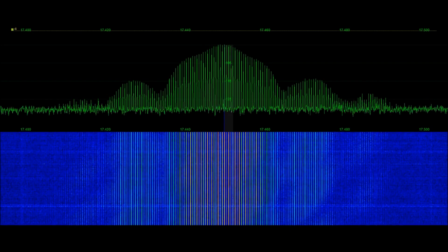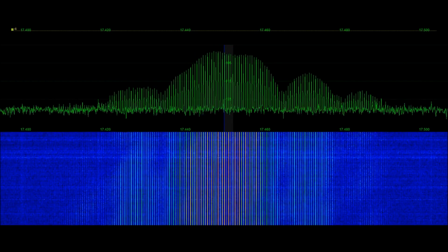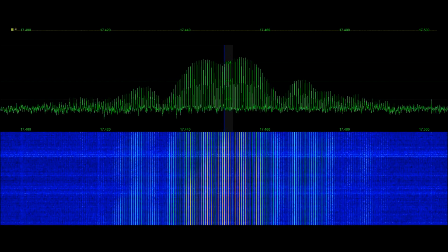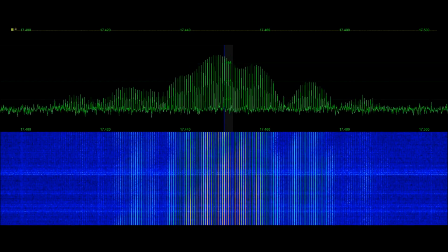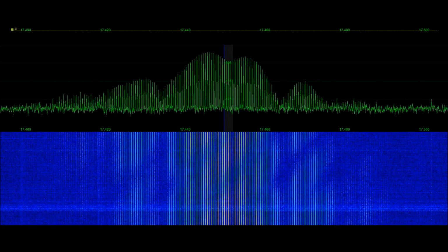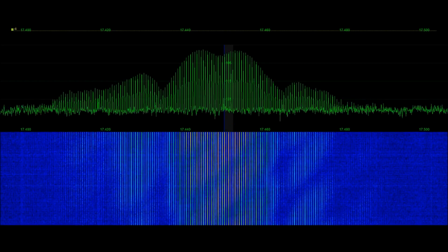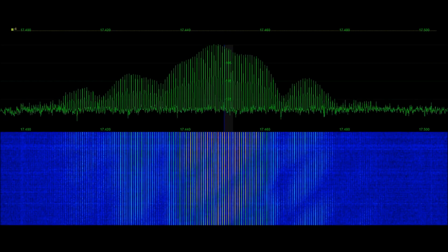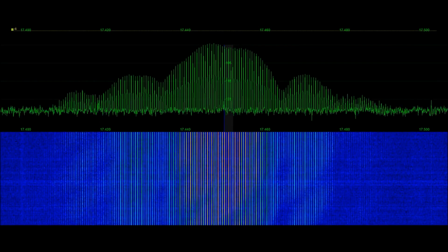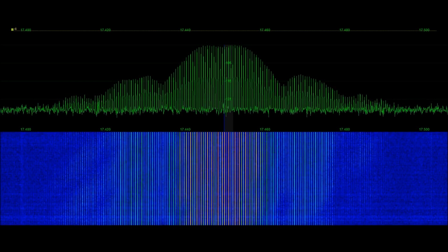And you can see the sidebands actually develop here, the upper and lower sideband of the main lobe that we're looking at. And this is really problematic because this is a Doppler radar, and the sidebands not only take away energy from the fundamental lobe, but they can also cause aliasing and actually curve into the main lobe and start to cause deviations or problems with how the radar is supposed to be seeing its target.